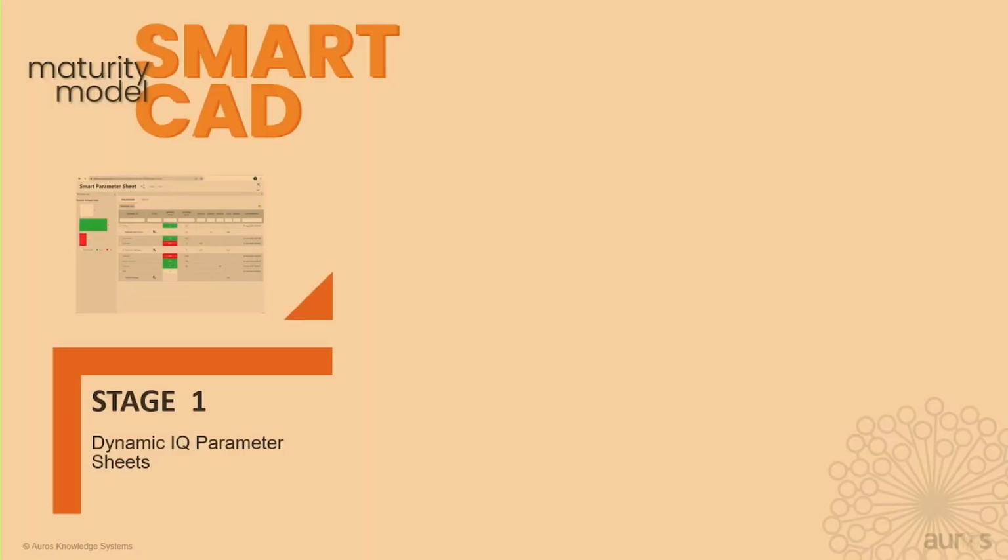This actually, the first stage, we don't even recommend that you model your knowledge and embed it directly into a CAD model. We recommend you create these dynamic parameter sheets and verify them outside of the CAD application for 3 reasons. 1, we want to verify that the models that you've created, not the CAD models, but the knowledge models, that the strategy that's been created is sound.